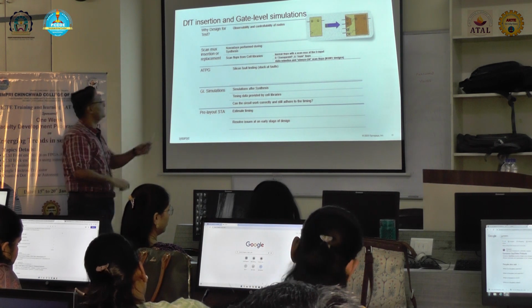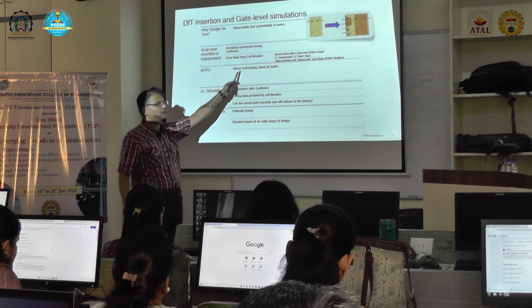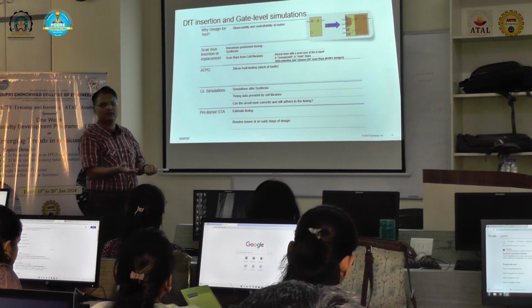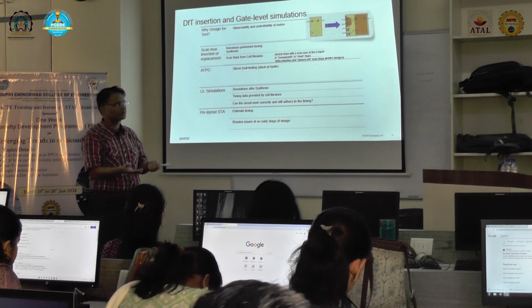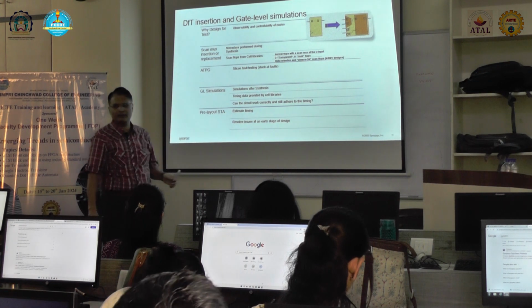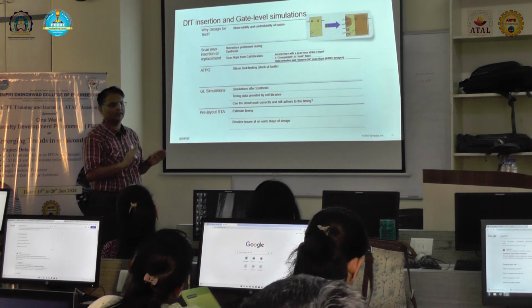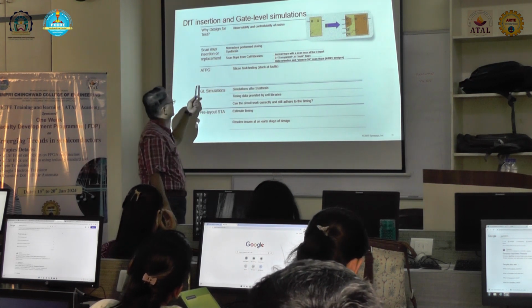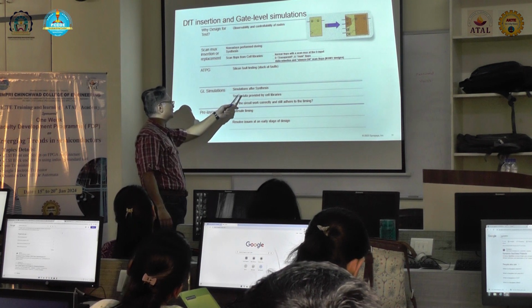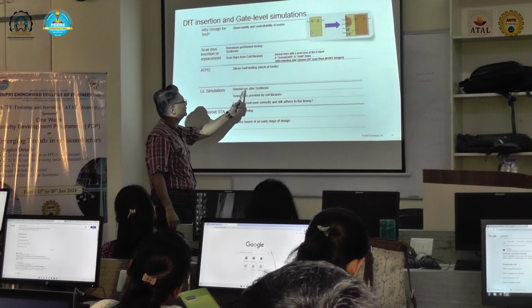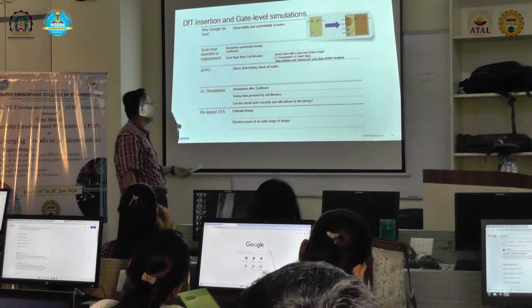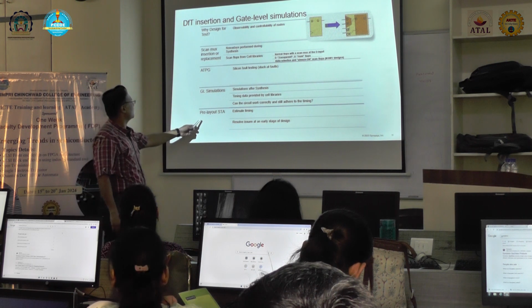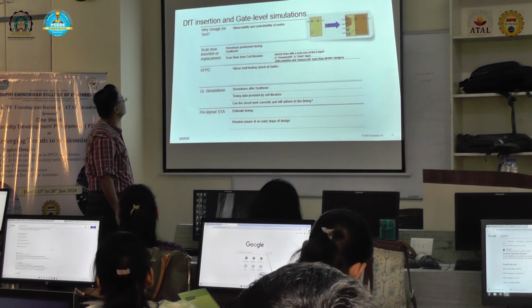For ATPG, we have covered ATPG already, that this is for silicon fault testing at the foundry. Once I have given the design to the fabrication, they have to run this ATPG to make sure that the fabrication is correct. So this is for silicon fault testing. Then gate level simulations, this we also covered. We simulate the netlist, that is what gate level simulation is. And then we do the pre-layout testing.